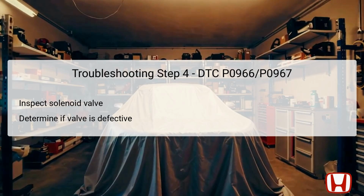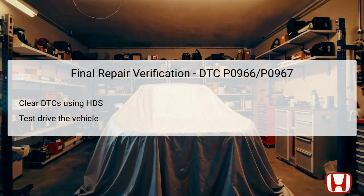Physical inspection involves checking the solenoid for any visible damages or irregularities, and functional testing should confirm its operational capability. If the valve fails to operate as expected under controlled testing conditions, it should be replaced with a new component. Replacing a defective solenoid valve is crucial to restoring proper pressure control to the CVT, thereby resolving any issues related to transmission performance.